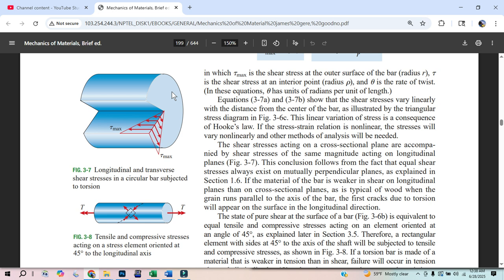It's like someone torqued a shaft and we see that it moved an angle. Think, hey, I want to know the circumferential distance it moved, because that distance, divided by this radians times radius, is that arc length. So arc length is the kicker on this derivation. That's the linking part, because this angle and this arc length right here is a similar triangle with your shear, which is a similar triangle to what you actually see for angle of twist if this is the full length of the rod. Hell yeah.